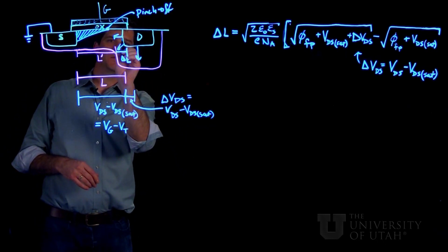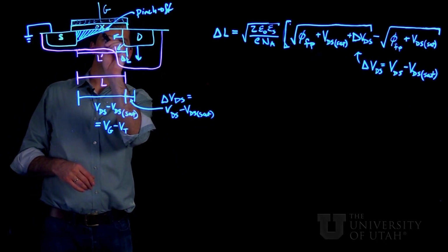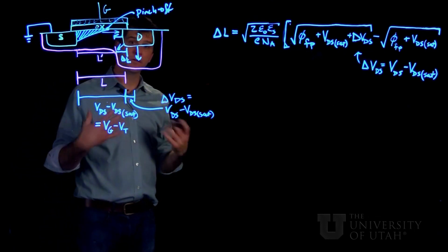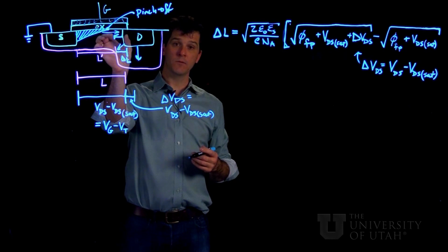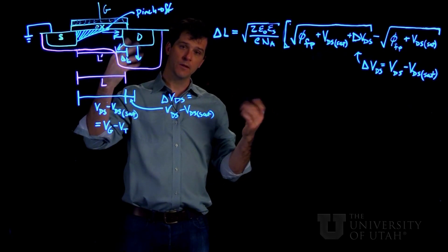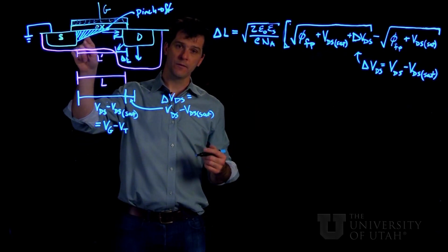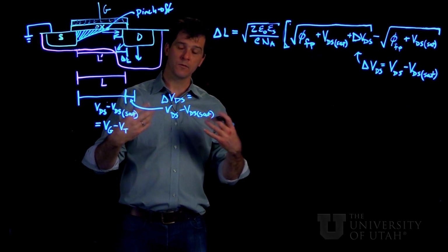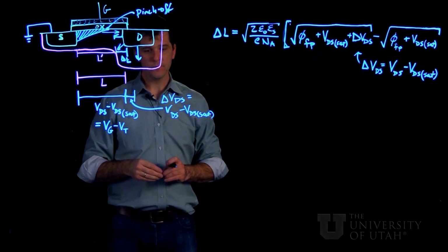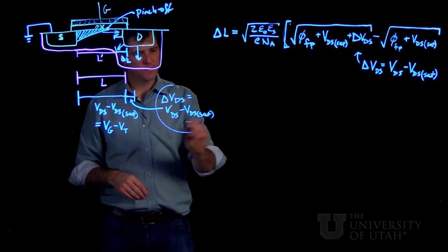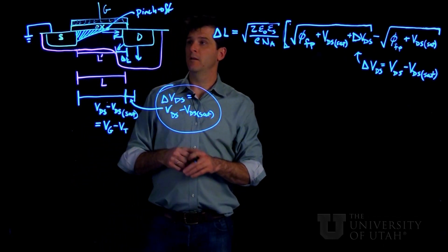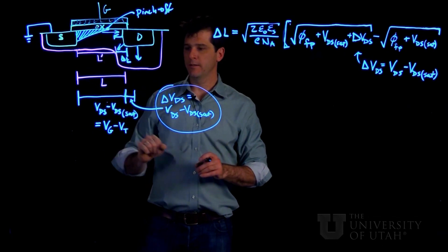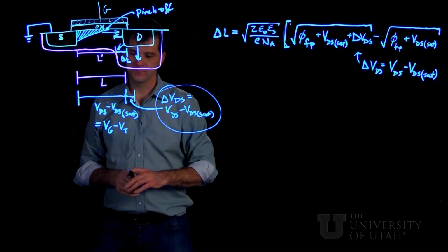And that means that part of the current flowing through the channel has to pass through a depletion width, which has very high resistance compared to the very low resistance where there's a total inversion charge. So that results in an additional apportioning of the total voltage applied here, and we've drawn this here in blue.